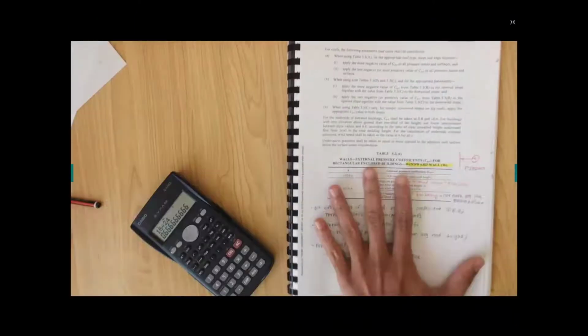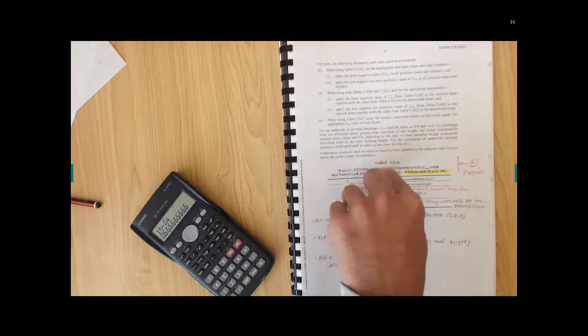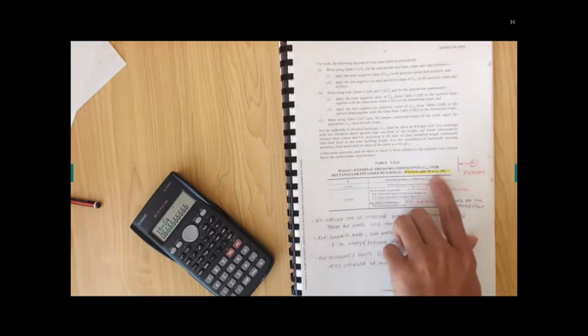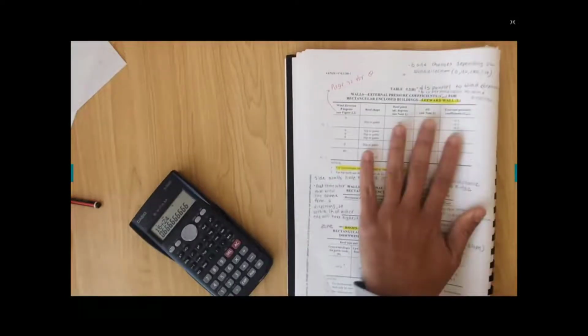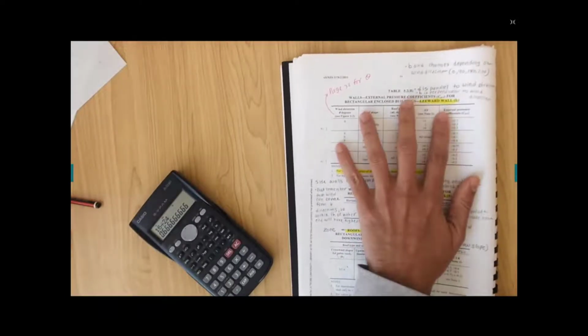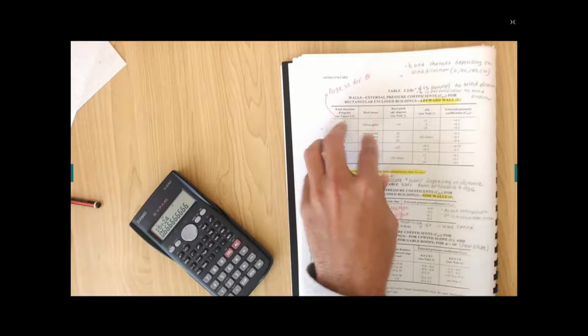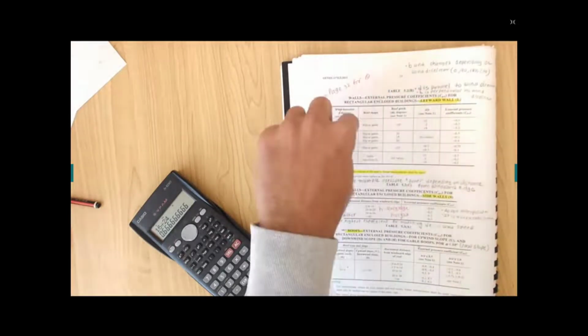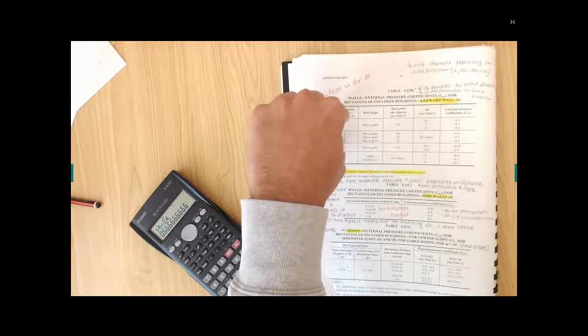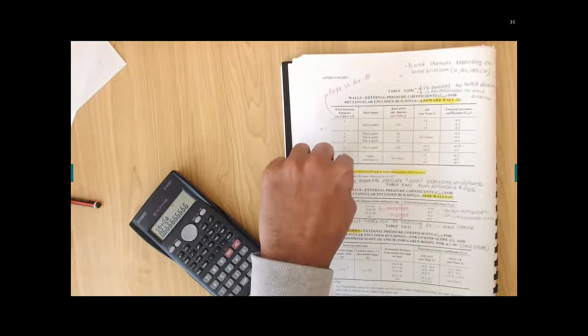I hope everyone is now in a position to use table 5.2a for the windward wall. And if someone asks you to find the CPE value for the leeward wall for any direction, you have these tables, so you are able to classify whether theta equal to 0 or theta equal to 90.